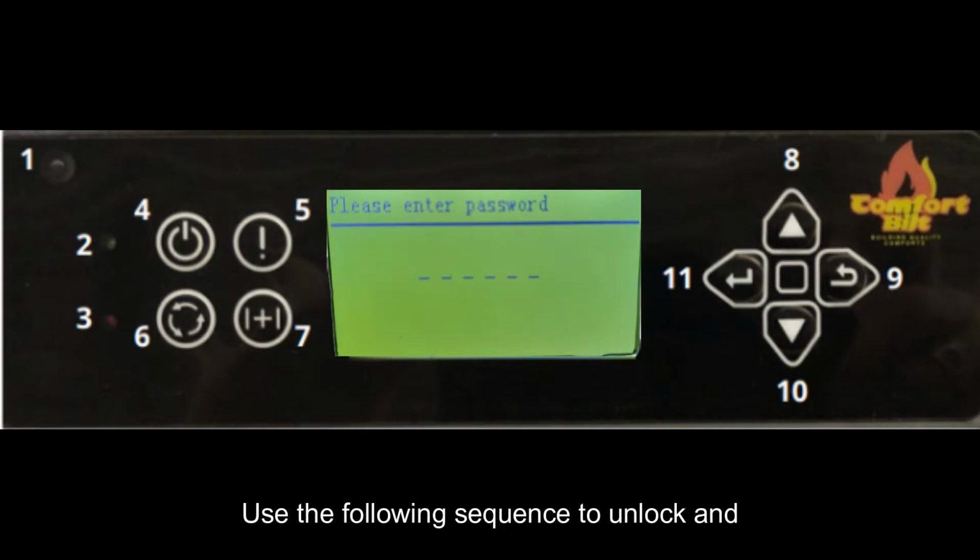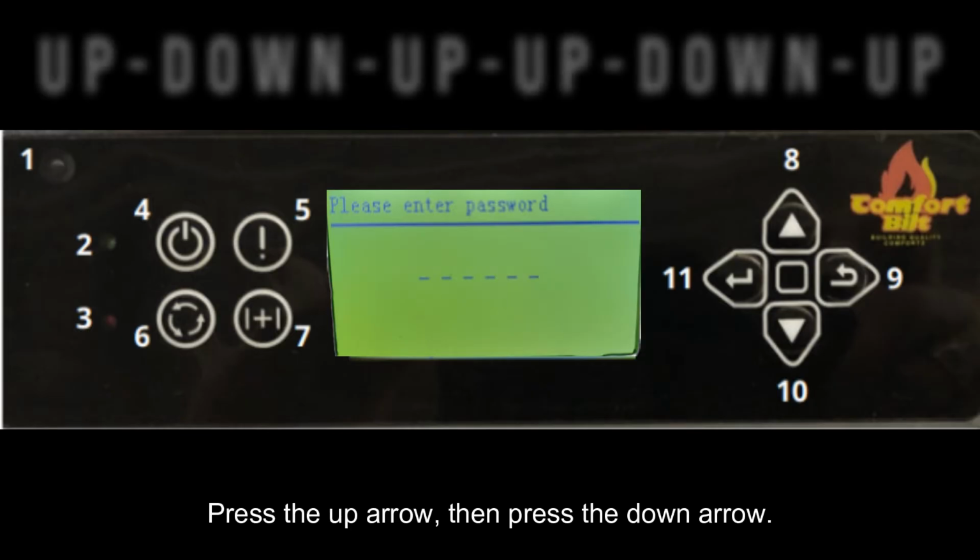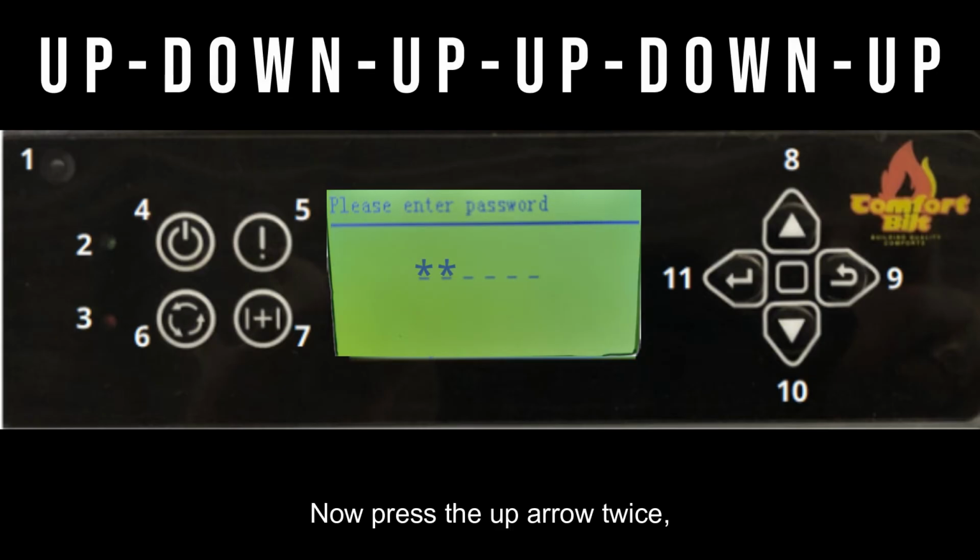Use the following sequence to unlock and enter this menu using the arrow buttons. Press the up arrow, then press the down arrow. Now press the up arrow twice. Then press down arrow, and then finally up arrow again. This should access the menu.